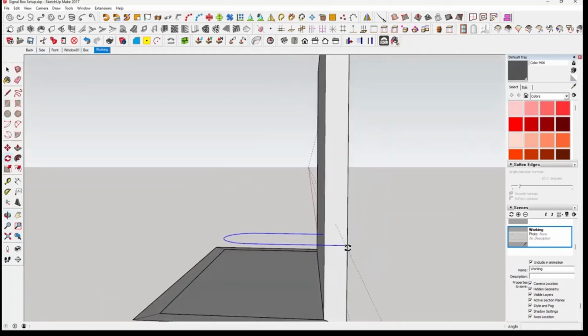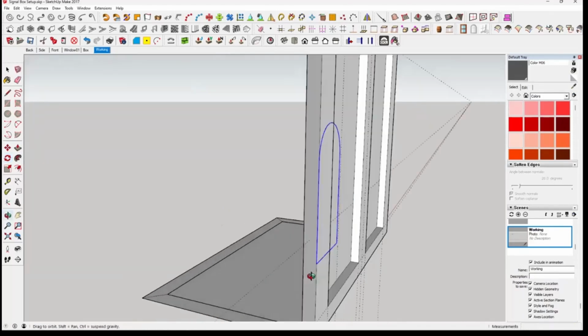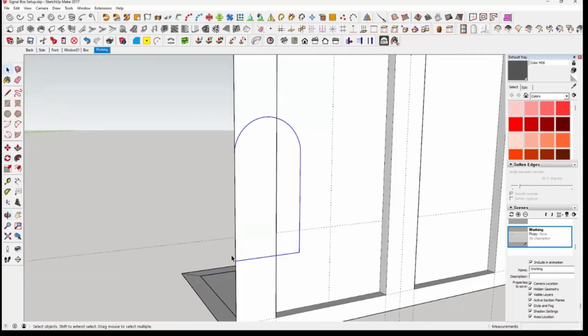So this one, we want to go on the corner, press the right arrow, constrain it on the x-axis. Click on, pull away, and just rotate. You can use a protractor. There we go, it's 90. If you look right in the corner, bottom right, 90 degrees. Or you can just start moving it, type 90, enter, and we're still on 90 degrees. There we go. So we want to go on here, we want to pick it.